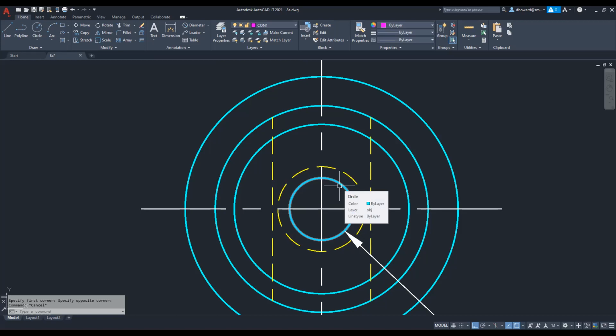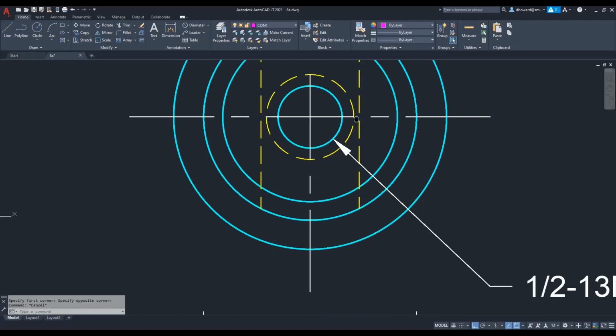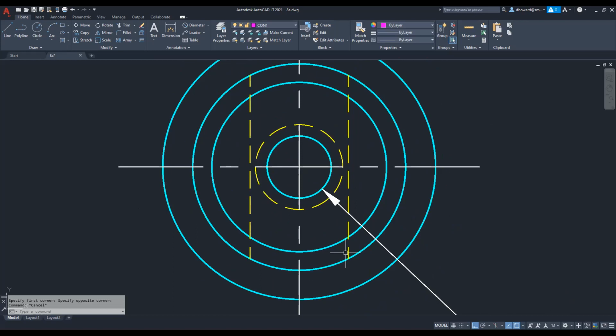And the diameter of this hole or the larger one is actually given to us by the size of the thread, which is 1/2 inch. So in other words, the bolt that would fit into this hole, a bolt that we are also going to make, is 1/2 inch in diameter. The two go together pretty tight. So basically, this inner hole is 27/64. The outer hole is 0.5. Okay, and so that's what you're going to draw.